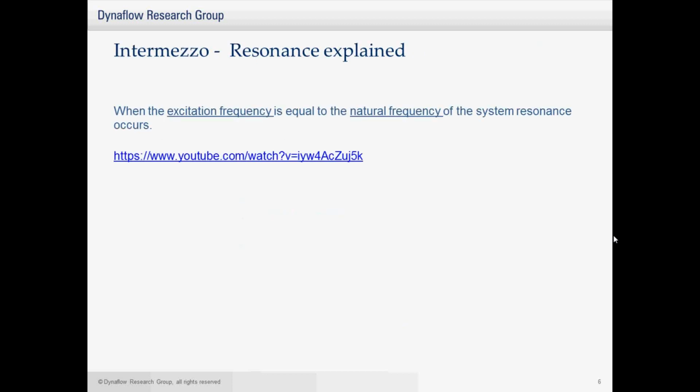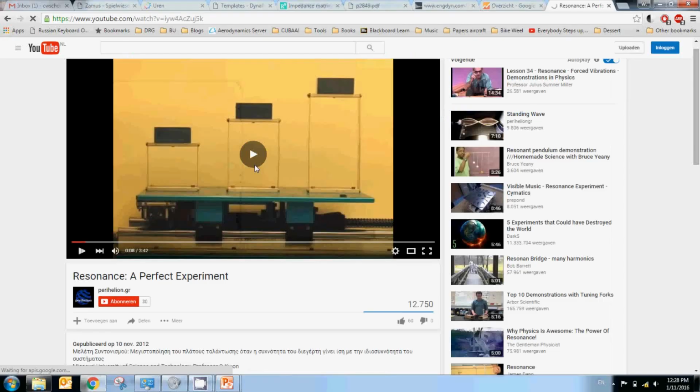But first, let's talk a little bit about resonance. Resonance is a critical aspect when you're doing pulsation and vibration analysis. You should really have a clear understanding of what resonance is. And basically the definition is when the excitation frequency is equal to the natural frequency of the system, resonance occurs. And I've a little YouTube video here which might explain this concept a little bit better.